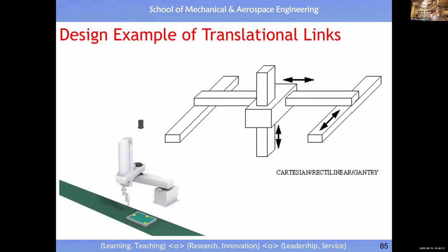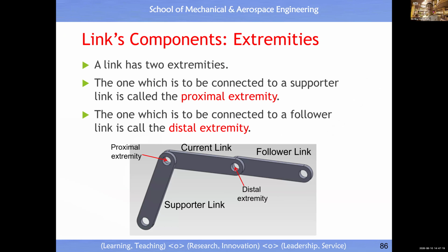So this is another example. A joint will constrain the motion. This is another convention in robotics: each joint will only enable one degree of motion. This one degree of motion could be rotary motion or translational motion. This slide shows you translational motion, so you see the link can, in this case, only undergo translational motion. Clear? And then what are the parameters of a link?